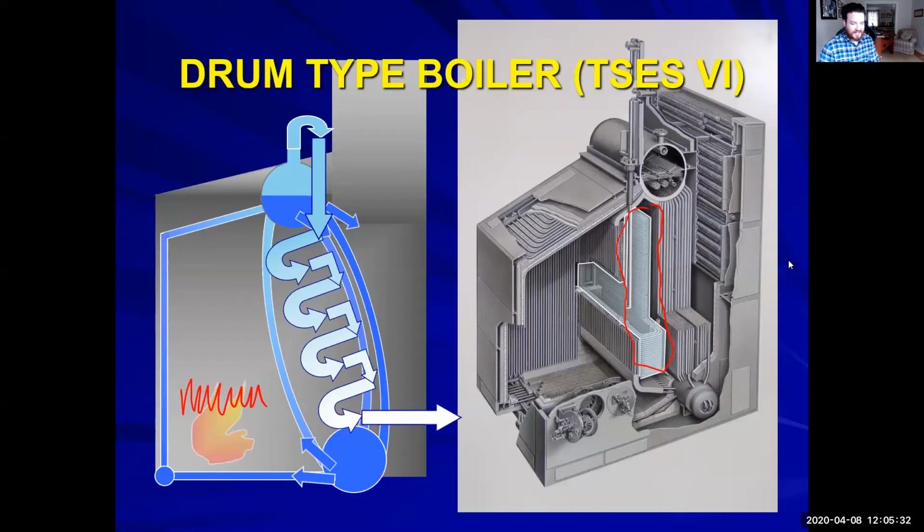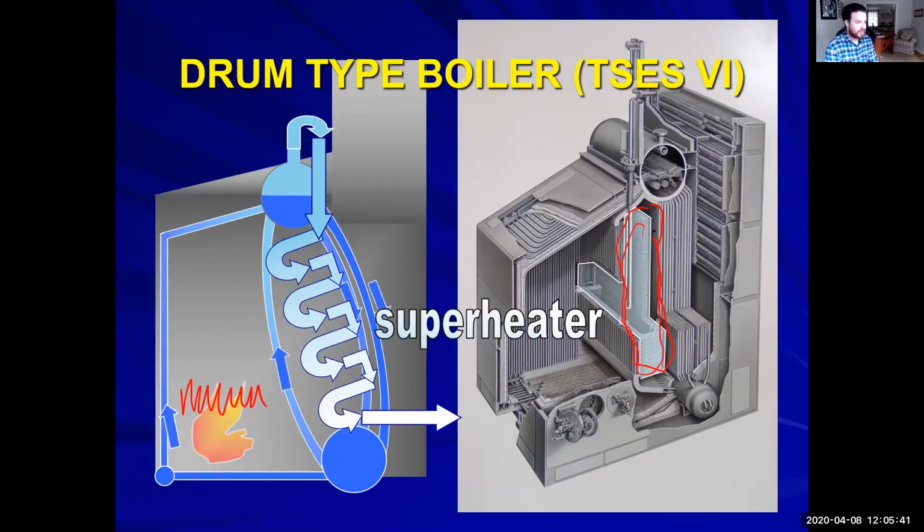So, as I said, here we have our superheater. Our superheater is located in this area in between the generating tubes. And then where I scribbled over here, why not have the superheater right on top of the flame? We're trying to make sure we have no water molecules, no liquid molecules inside that superheater. Why not give it the best possible ability to heat up? Wouldn't inside those flames be the best spot for it?